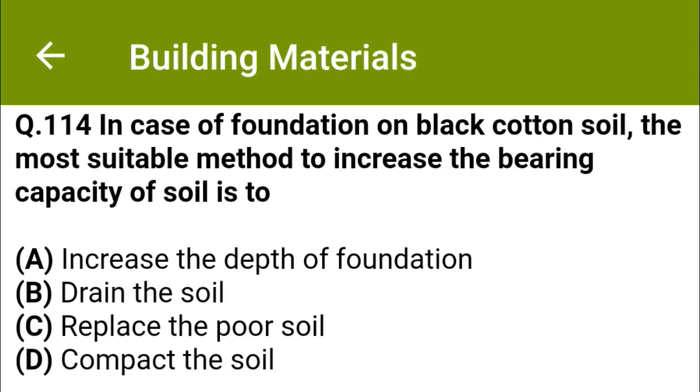In case of foundation on black cotton soil, the most suitable method to increase the bearing capacity of soil is to: option A increase the depth of foundation, option B drain the soil, option C replace the poor soil, option D compact the soil. The correct answer is option C, replace the poor soil.